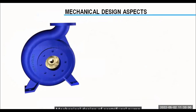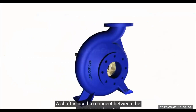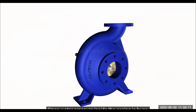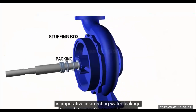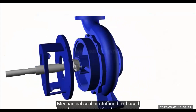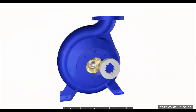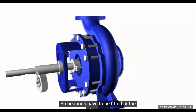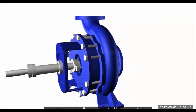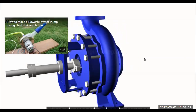Mechanical design of centrifugal pump is always challenging. A shaft is used to connect between the impeller and motor. Since water pressure inside casing is huge, a proper sealing arrangement is imperative in arresting water leakage through shaft casing clearance. Mechanical seal or stuffing box-based mechanism is used for this purpose. Impeller is mounted on bearings, but at suction side of impeller, it is not advisable to fit a bearing since it will block the flow. So bearings have to be fitted at the other end. This means impeller is mounted like a cantilever. For high flow rate pumps, a bearing housing with cooling oil is necessary for improving life of bearings.